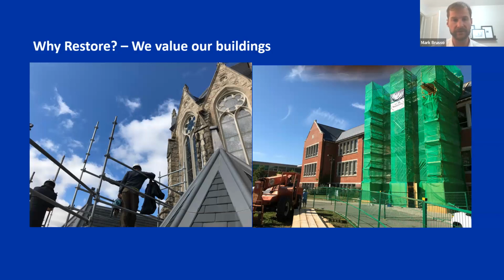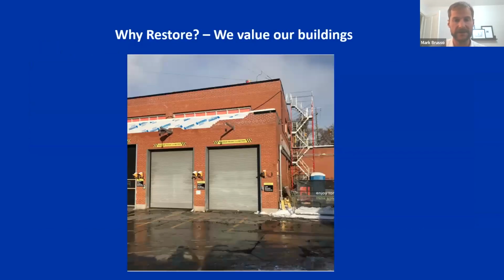And that's one of the beauties about masonry, it's very easily restored because it's so many of these individual units of brick put together. And we are able to do so many things to restore brick. We're able to repoint the brick. We're able to install helical ties. We're able to rebuild certain sections that have deteriorated. And so it's very easily restored.